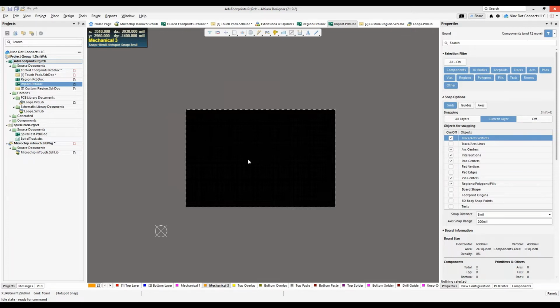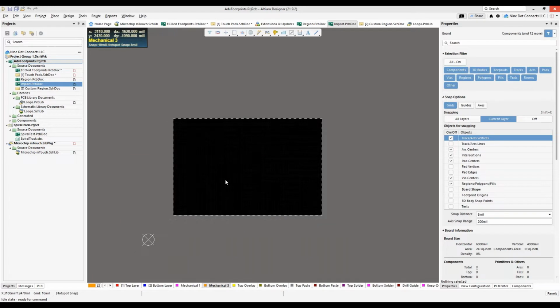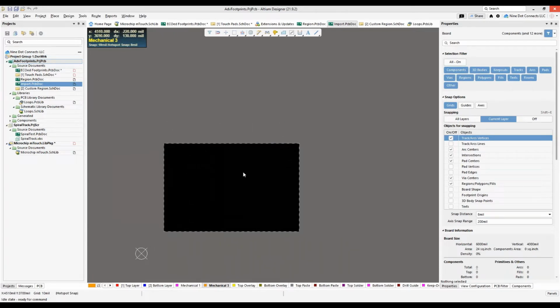So the short of it is that when we are trying to deal with this, you probably want to tell Altium to treat the 0 point somewhere up here in the top right corner so that there's nothing that gets into the other quadrants. And just be ready for something that might come in odd. And sometimes you just have to close out Altium, or you do Control-Z to undo it. So that's just kind of my piece of advice on this.